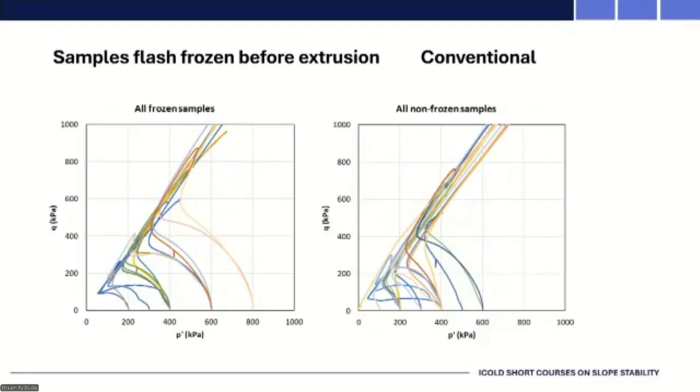I think the disturbance associated with transporting these samples anywhere is much smaller than the massive amount of deformation that you can cause. I showed that photo earlier where the level of the tailings inside the sampler was lower than outside. So that is our problem, not transporting the sample elsewhere.